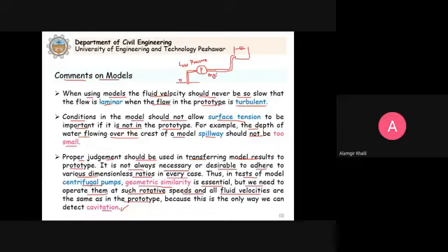Now, we can study in detail why this cavitation occurs. There are several reasons for that, but whatever the reason, what happens is that the low pressure should not drop below the vapor pressure, because in that case the water will boil.